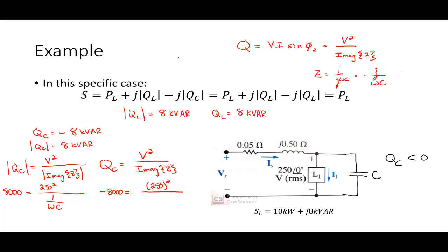So if I look at my impedance relationship, because I'm talking about a capacitor, I'm talking about something that is imaginary to begin with, but the imaginary part of that Z is negative 1 over omega C. So we notice that the minus signs cancel each other in that relationship. Essentially, these two relationships are now the same. I just wanted to point that out because you've got to be a little bit careful about these signs. In your results, you should never get a negative capacitor value or a negative inductor value. If you did, you probably got the signs wrong in terms of whether you were looking at the absolute value or not.